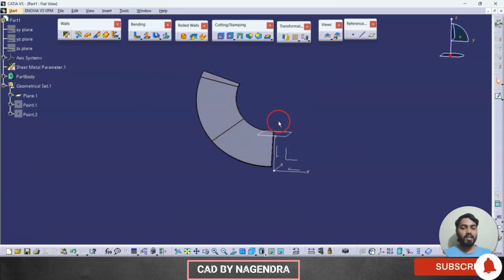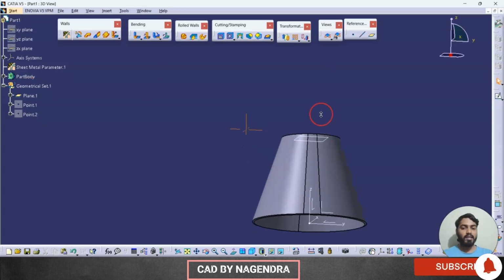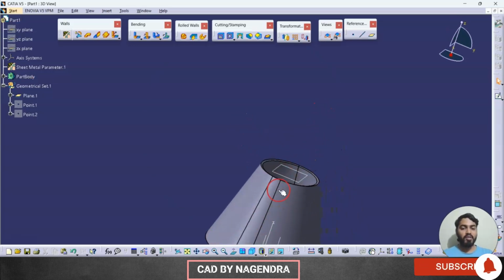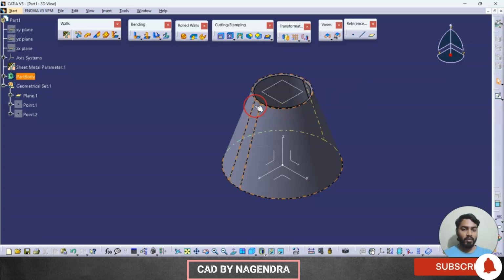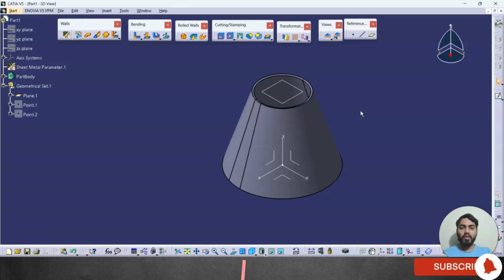After cutting this blank sheet in this shape, we can bend it like this and make any joining operation like welding here. So I hope you have understood about the conic hopper. It means we want to add sheet metal material between two circular profiles which are at different heights and different dimensions, both circular in shape. There we can use the conic hopper, and we need to create 2 points where the joining line or joining position should take place. So that is about the conic hopper.